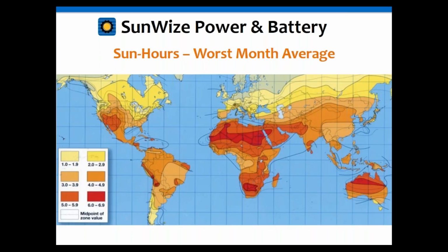And here's just a general idea of the map. Again, if you look at the color coding, you'll see that some areas can be higher than 6 sun hours a day. You're talking very center of the deserts, which aren't really going to be applicable in the U.S. In the U.S., you might find 5 hours maybe in parts of Texas, definitely throughout Arizona and parts of New Mexico. You might see numbers that high even in Southern California. Generally, though, for most of the U.S., you're going to be somewhere between 2 and 4. In areas around Seattle or Boston, it might be a little less, maybe about 1 to 2. They get some really lousy sunlight in those areas.